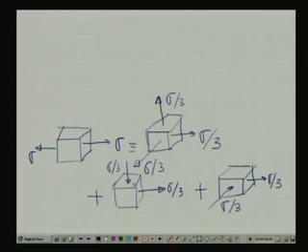It is a case of pure shear sort of thing, and if you look from one side, negative another positive, it also gives you some sort of distortion in the shear. So, this particular situation creates a change in the volume, and these particular situations create a distortion. There is no change in the volume, but distortion of this particular element.